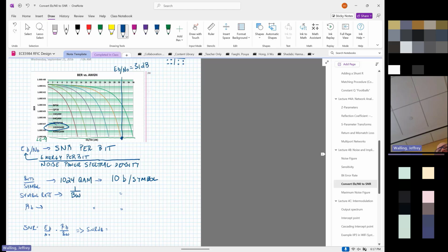They've added some additional features since then that go down to even 5 megahertz and below, but almost everything is a multiple of 20 megahertz. And this corresponds to a symbol period of about 6.25 nanoseconds.